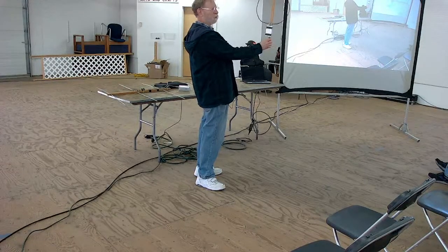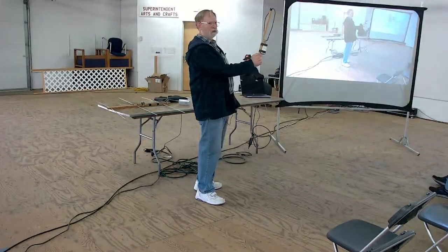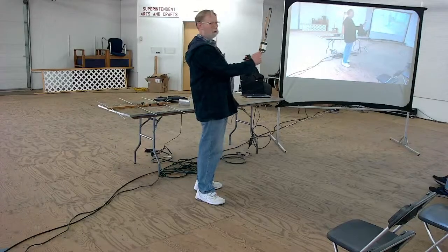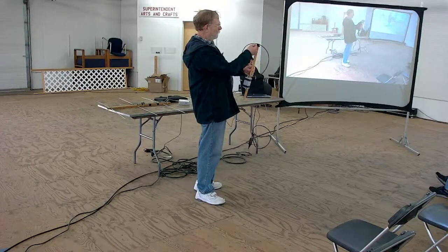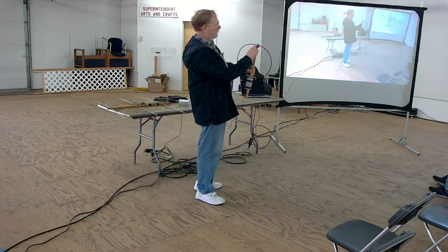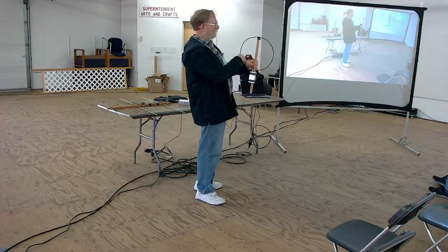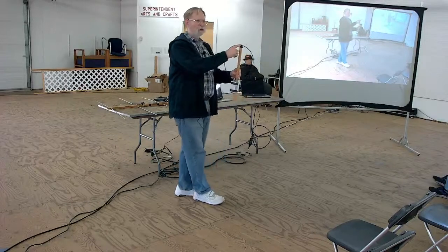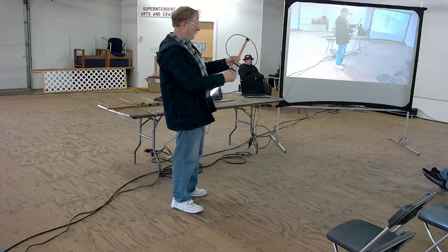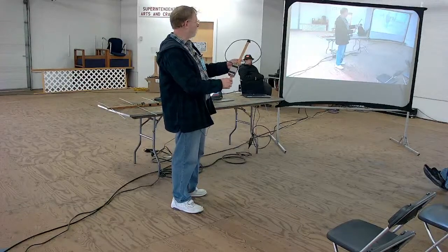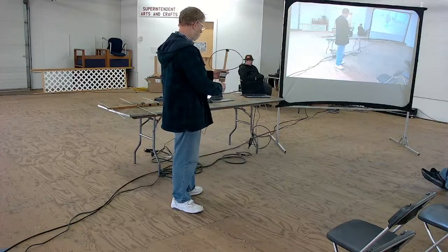And it doesn't matter whether it's this way or that way. You're going to get a sharp null off of both directions. And so in this case, what you're doing is you're trying to pick up the signal with a null. And so this is just a piece of coax, and you can't tell, but underneath all this electrical tape here, I've cut the shield. And so it's actually shielded all around, but the shield is broken in one spot, which allows the center conductor to act as a shielded magnetic loop. And then inside the box is a tuning capacitor that is used to make the antenna work well at HF frequencies.